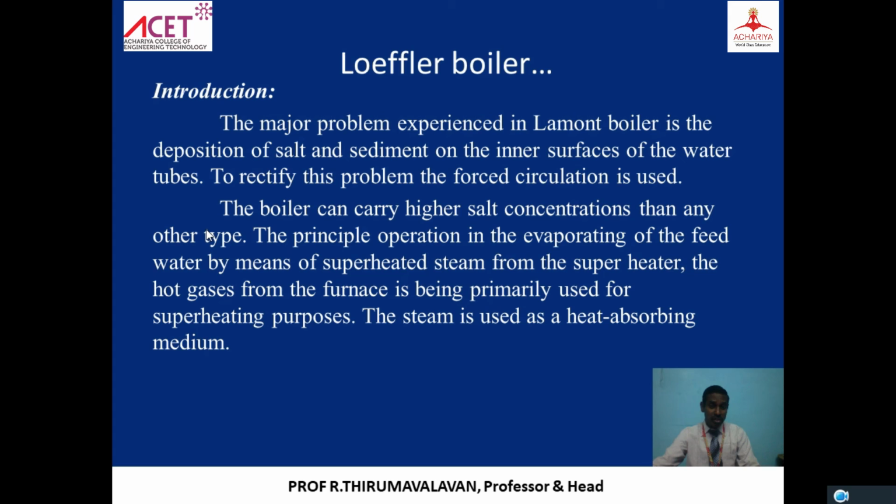But here we are using two pumps, right? The principle of operation is evaporating feed water by means of superheated steam from the superheater. The hot gases in the furnace are primarily used for superheating purposes, right? The steam is used as the heat absorbing medium.